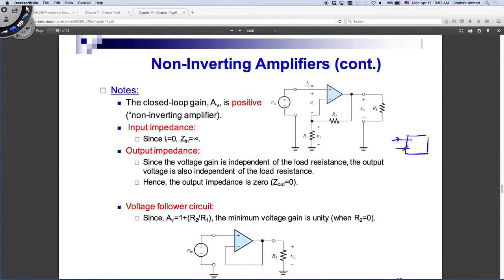And then the other thing that makes our life easy was, if we're able to make the voltage between these two nodes 0, then I can close the loop around here and do some calculations, relating input to output using the currents flowing in these various resistors, right? That's the beauty of what we wanted to do. Otherwise, there's no way to close the loop here, because I have an open circuit between these two terminals when I leave the op-amp by itself.